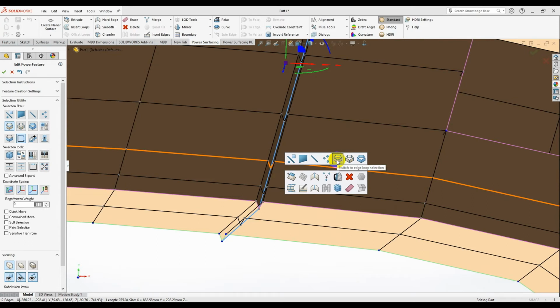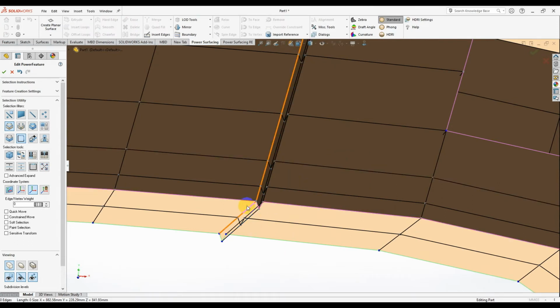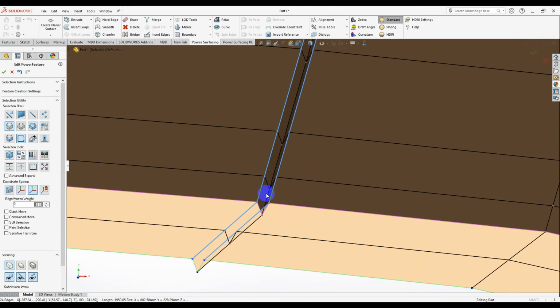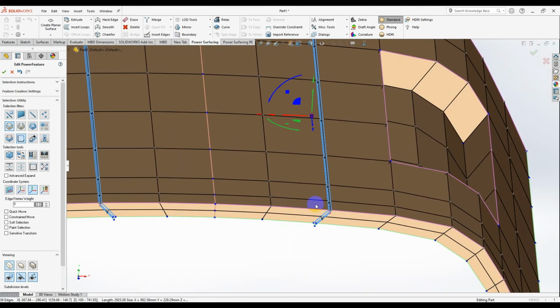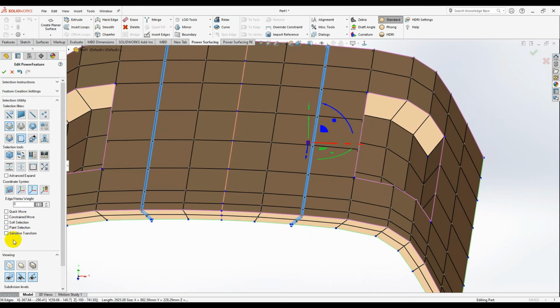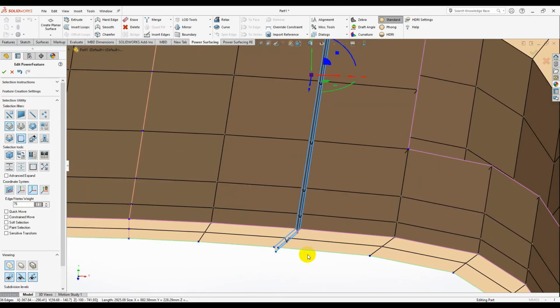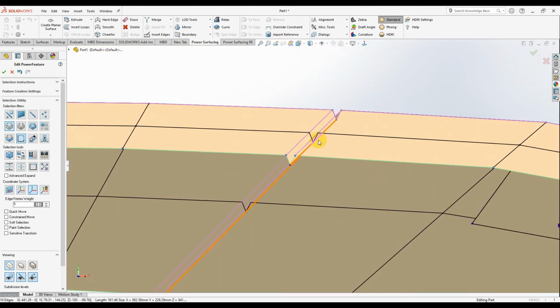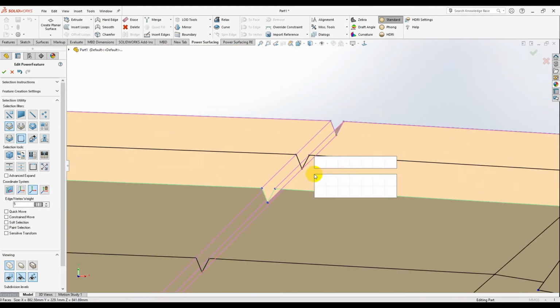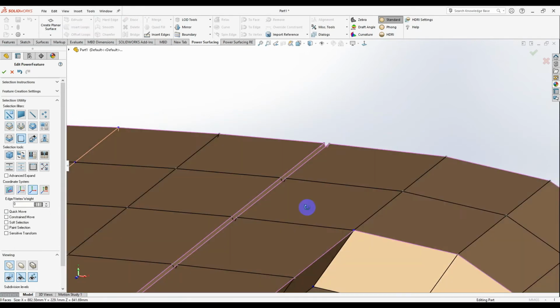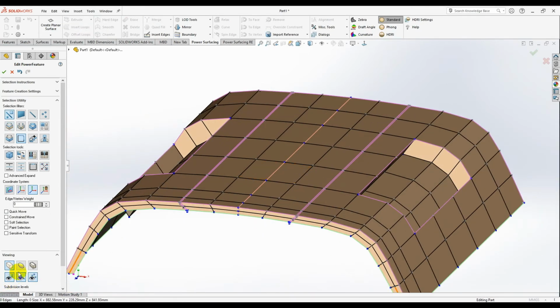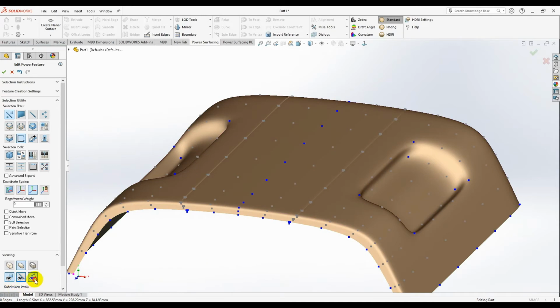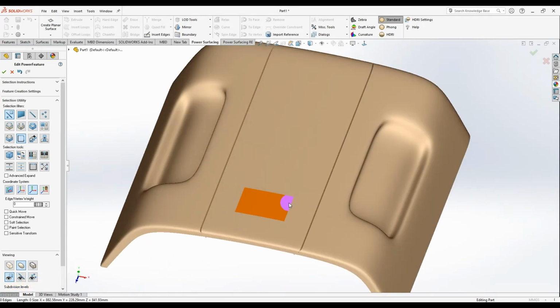Now using switch to edge loop and selecting the 3 edges like this, let's type 74 and press this arrow at 1 to apply. Okay, now I can get the top or the front view, and you can easily see it has created more detail on the shape like this.